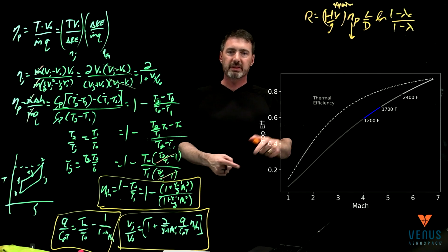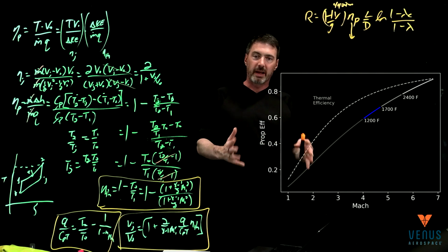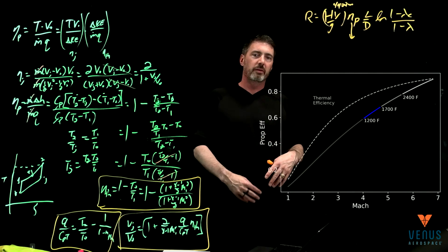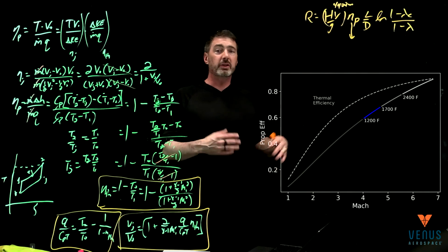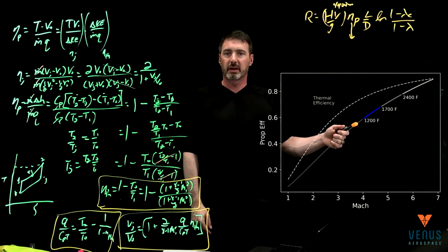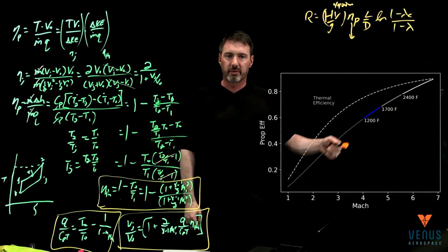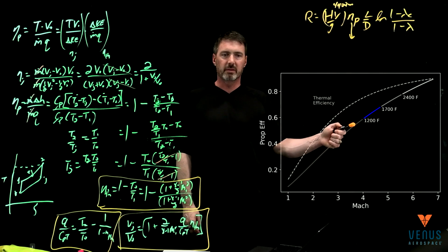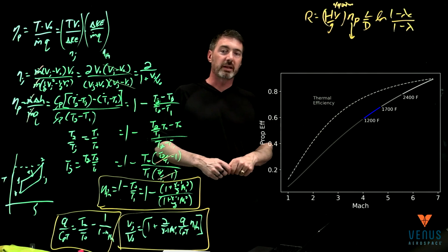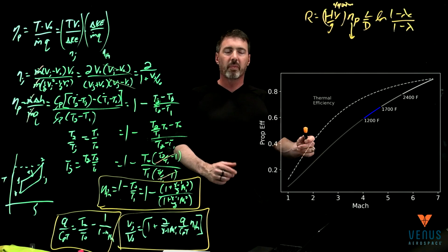Based on that, you could calculate the temperature that the air is after it's been rammed in, because that's a material choice. You could choose all of those speeds, fine, but once you hit Mach 4, the air is now 1,200 Fahrenheit, which would mean stainless steels or titanium, that's about its limit. So this gray line is everything titanium and steel. What I've highlighted here in blue would be saying, actually, I'm okay making my engine out of Inconel. So this blue represents an Inconel range.